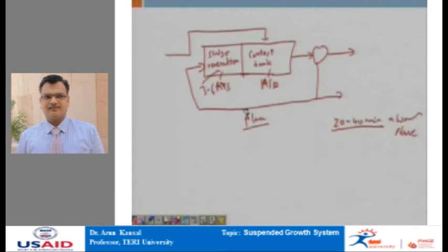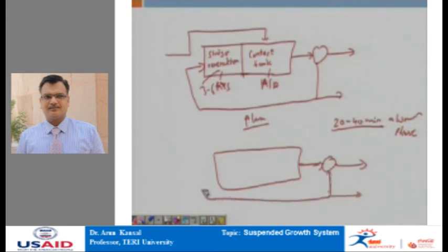So, in a normal aeration tank which was used earlier, suppose we have an increased amount of wastewater flow or increased loading. What we simply do is that rather than wastewater coming like this, we change the piping layout, cut this off, put it here. The contact time is about 30 minutes to 90 minutes, and the rest of the aeration tank, 3 to 6 hours, is for the sludge re-aeration.